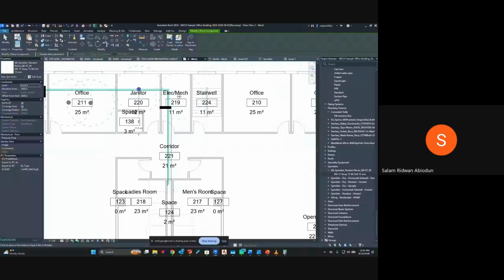I told you, you cannot put anything water in electrical room. We are not putting anything here. You cannot extinguish fire from electrical devices with water. It's not possible. So you use maybe cleaning agent, or you use DCP, that's dry chemical powder. That's what we talked about before now.